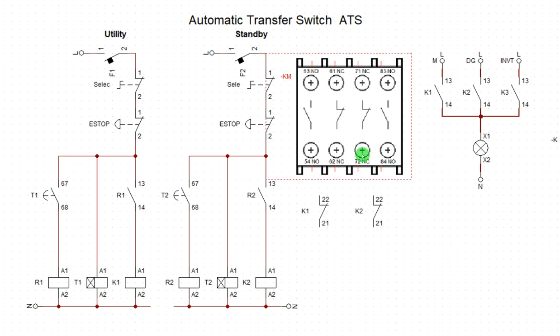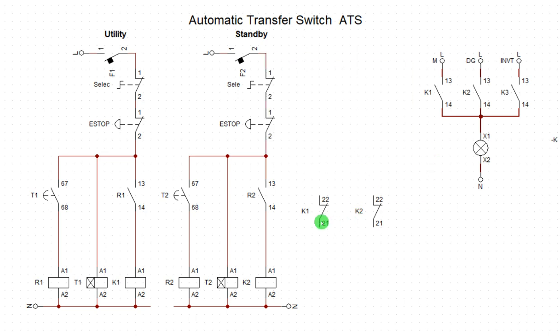So we take it away. We now insert the auxiliary contact here. How do we put it? Take away here and fixing one here. So before energizing this, you have to go here and interlock before coming back here. So the same thing applies here.